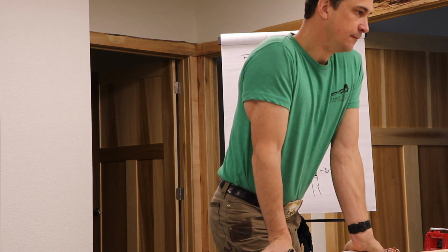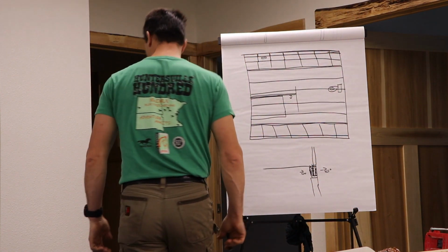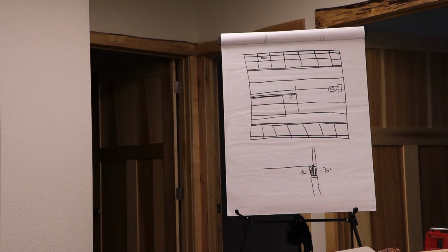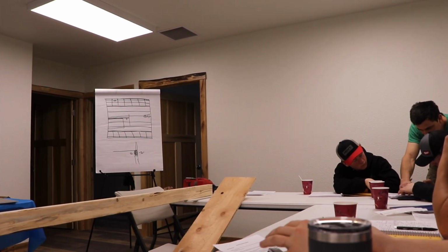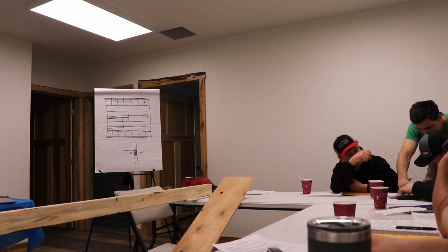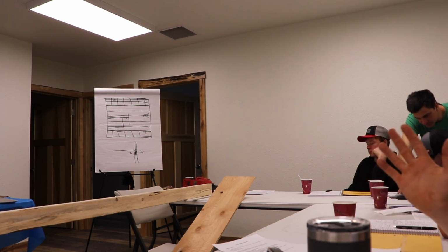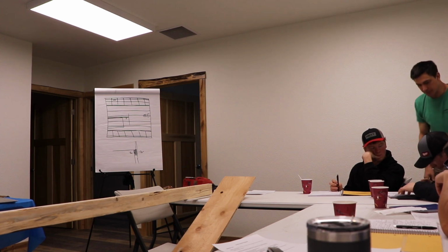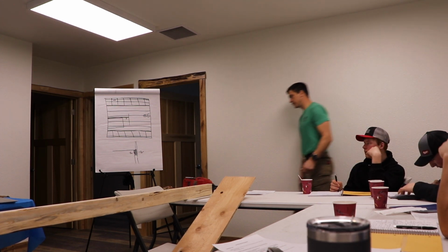Okay, so we follow our 70 degree line until we intersect the 35% curve. It'd be halfway between 30 and 40, and then you follow that across. It would be about a 40 degree? Yeah. 40 degree dew point.